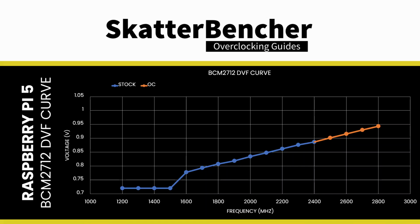When we increase the upper limit of the ARM frequency to 2800 MHz without adding any voltage, we find that the voltage also increases to 944 mV. That's useful information because it means we can increase the frequency without worrying too much about the voltage.